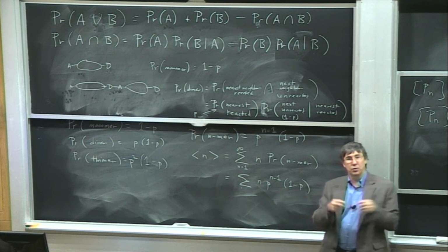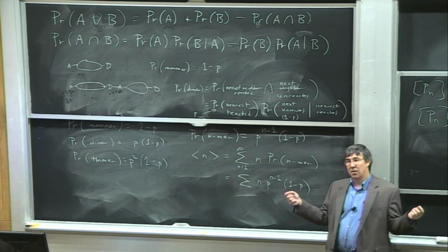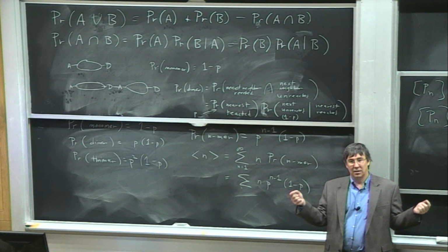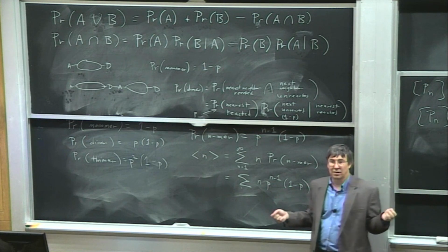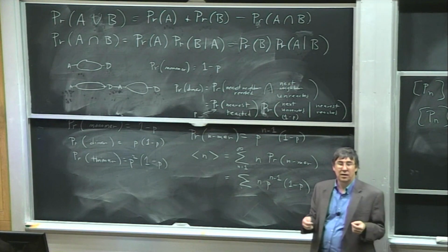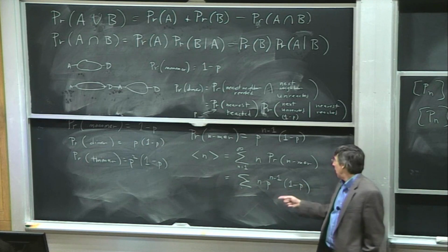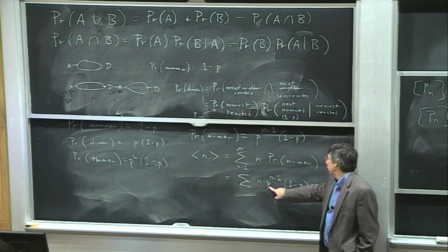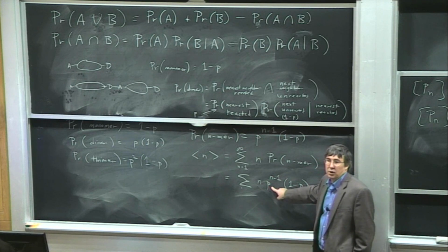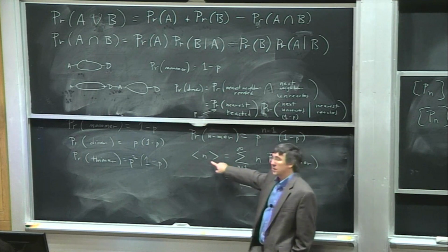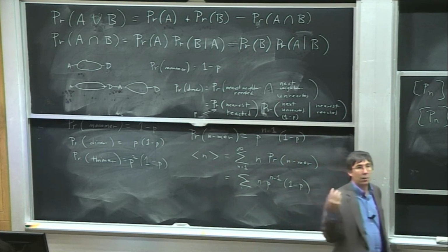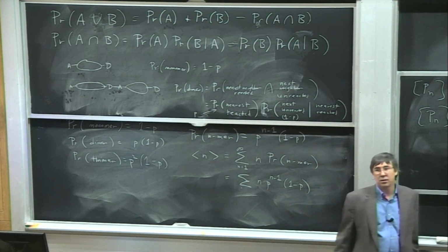If you make the polymer too long, then it's going to be hard to dissolve it. It's going to be hard to handle. It's going to be solid. If you make it too short, then it may not have the mechanical properties you need for the polymer to have. So there's some optimal choice. So you typically run the conversion until P reaches a number so that this is your optimal value. But then you care about what's the dispersion about that optimal value.